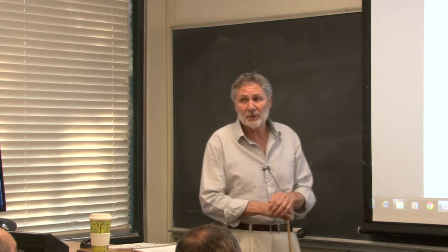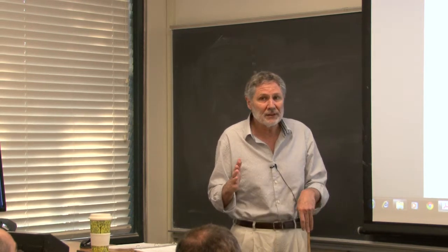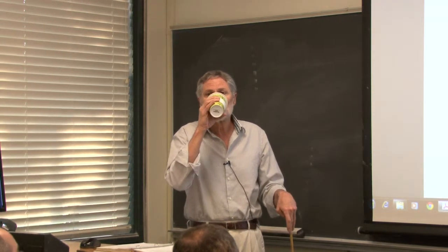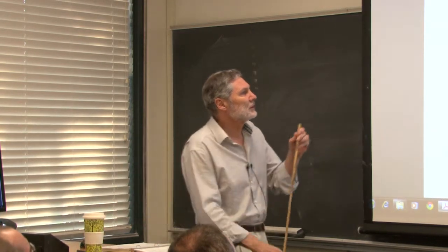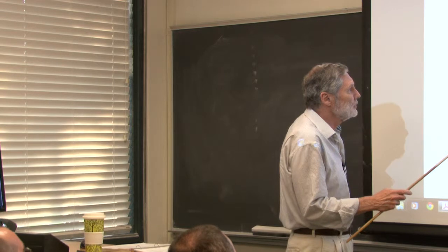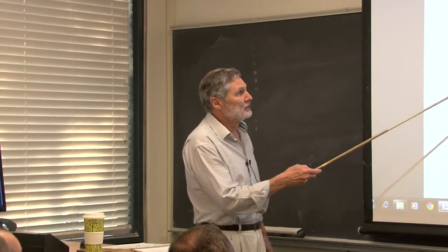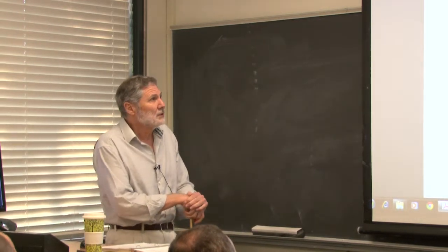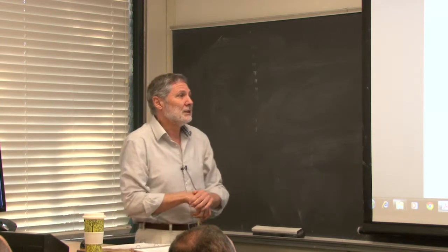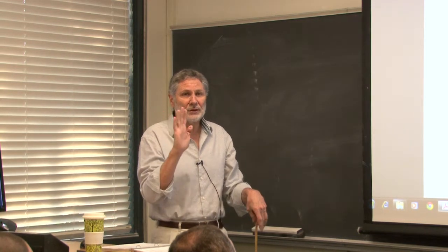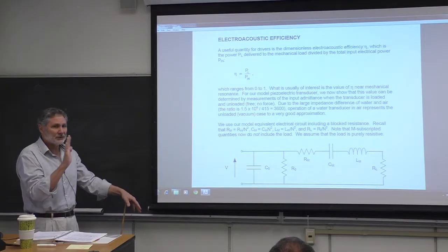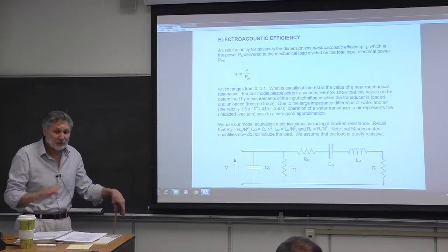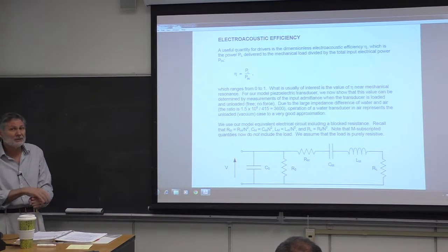Okay, water is where you ultimately want to use it, of course. Why would you test it in air? Well, compared to water, air is like a vacuum. Quantitatively, you can see that with the acoustic impedance. It's 3 orders of magnitude difference here. Much larger impedance in water than air. So almost always, if you want to test a sonar transducer, a projector, a driver, under the conditions of no load, what we call free, 0 force, a free, that's one of our important special limiting cases.